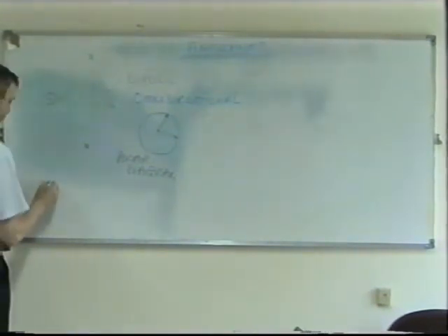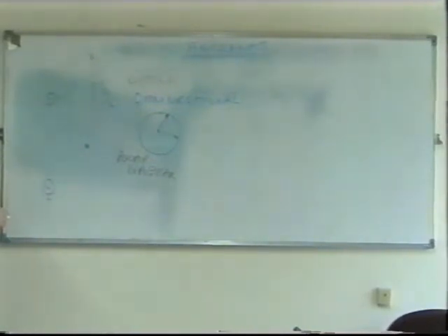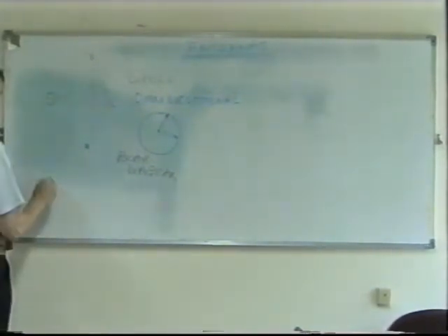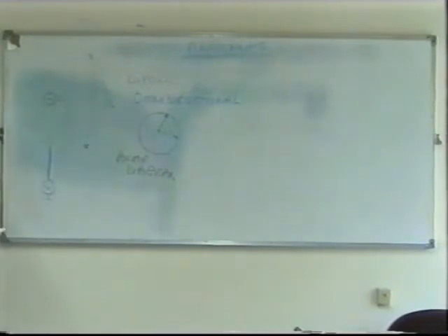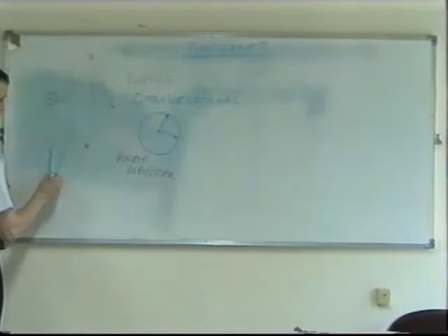We also talked about a quarter wave antenna. This is where one side is grounded of our transmitter, for example, and the other side is connected only to a single conductor. That conductor need only be, if we were to measure the length of it, a quarter of the total wavelength, λ/4. Because it's assumed that the other quarter is actually reflected in the ground itself.